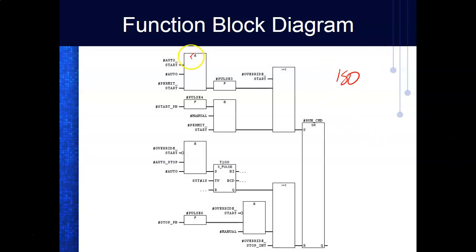So this is what we call an AND. It's a block. That means if this input is true, and this input is true, and this input is true, then it'll generate an output. This is a pulse detector. So if you came up through digital, if you understood digital electronics really well, this would be the language for you. This is the one you could understand.